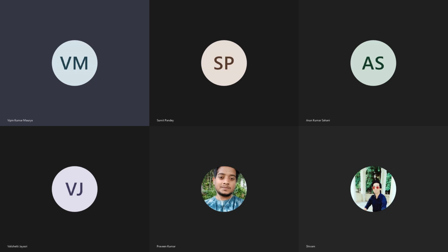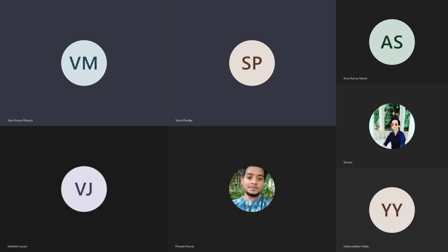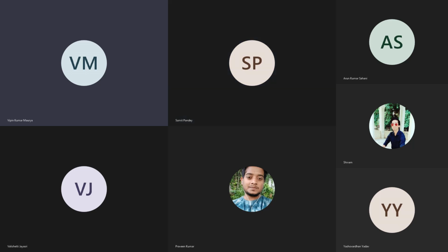Okay, in the next 3 minutes, try to find where this location is in India. That's our college, sir. NIT. Yes. So we are calculating for that location. We have x naught, y naught, z naught as the x, y, z which you have calculated, lambda naught and phi naught as the lambda and phi which I have given, and for x, y, and z, just subtract 5 from x naught, y naught, and z naught. Now try to calculate what values you get for E, N, and U.